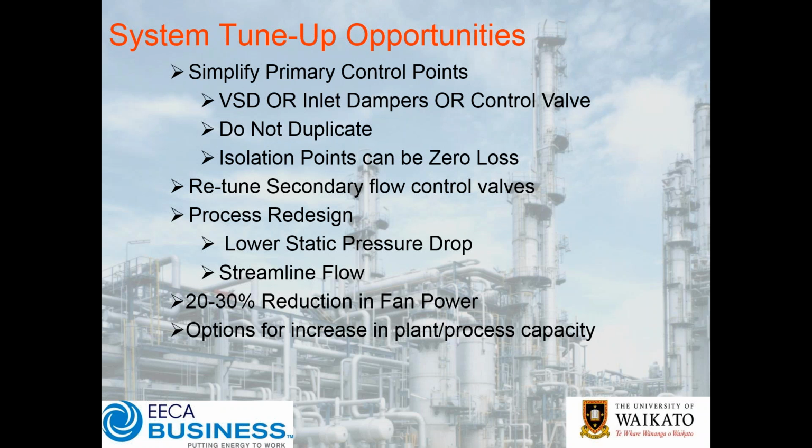And often, if you pay a little bit of attention to detail on the airflow upstream of how this air is distributed across multiple inlets, getting good duct design, good layout of that, is far more effective in the long run than having all these multiple secondary control valves that can be tweaked and played with. And so you can go through and tune the whole system only to find that an operator on night shift had all the best intentions in the world of improving things, thought he'd have a go, and in many cases it can end in disaster, and then you've got to start all over again.